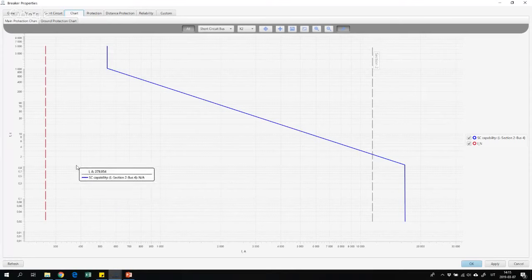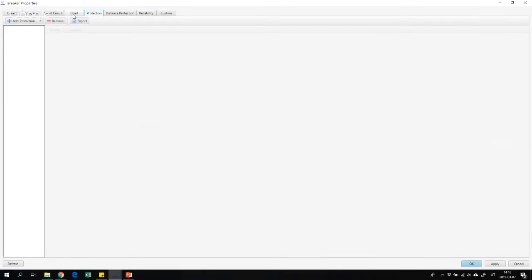So on this diagram, I can work with protection relay selectivity. For working with protection relay selectivity, I need to have information about all the currents, starting from load flow current. Then there is a short circuit current, which is depicted in this gray line, and also I need to know information about my cable capability, because protection should protect equipment in the network, and the cable also needs to be protected by the protection relay. So our relays should be capable of disconnecting before our cable melts down. So when we work with protection coordination, we will evaluate this.